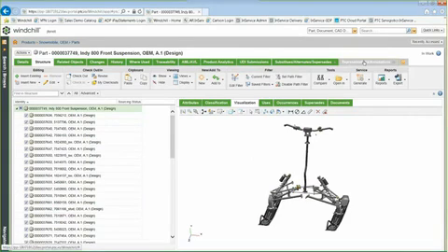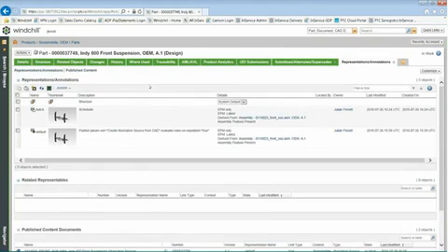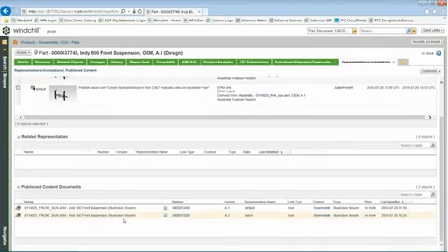Windchill allows me to navigate to our Representations tab and create publish jobs in order to use that information within Creo Illustrate. So here you can see, if I scroll down to the bottom, I actually have 2 jobs that I've created here, 2 different types of versions of those jobs that I can import directly into Creo Illustrate. It contains the geometry and it's very lightweight and file sized. So let's go ahead now and jump into Creo Illustrate.